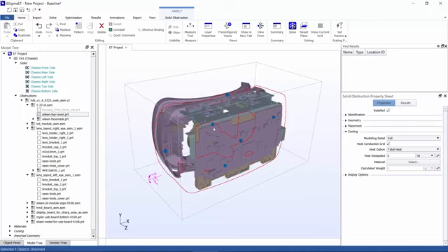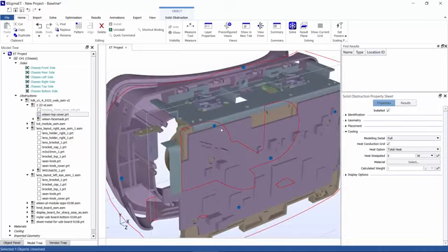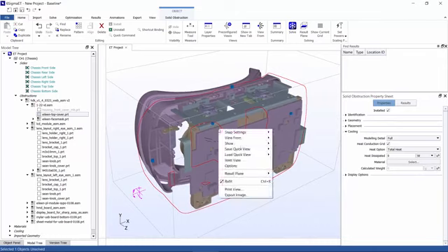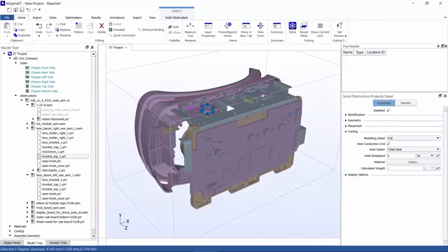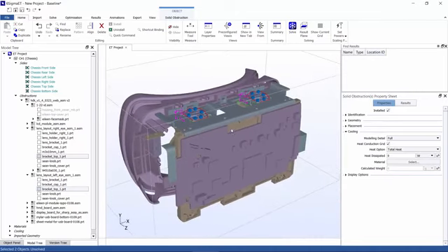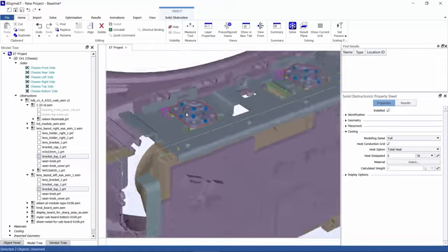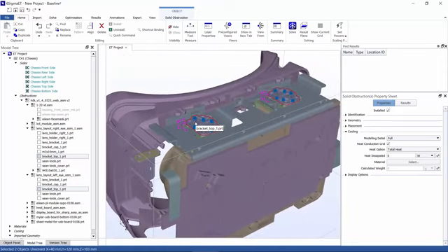And so now we can see all of these mechanical components and brackets that hold this together. And now we can identify objects that aren't thermally relevant. We can see these two brackets at the top of relatively complex geometry with curved surfaces and holes. So this will take a significant amount of grid to capture. We have an option on the right-hand side of the property sheet to adjust the modeling detail. This gives 4 options: full, approximate, ignored, and decorative.